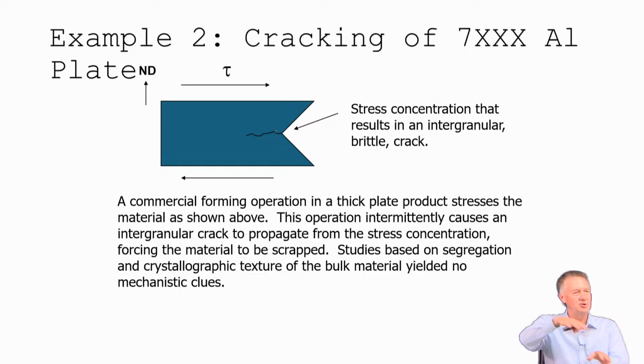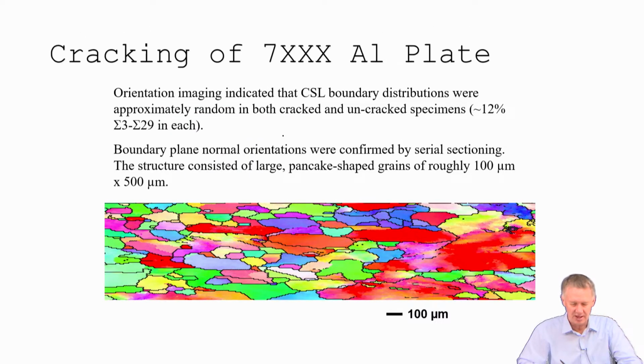They do the whole expansion procedure, and you get a crack, right, where you have an overlapping piece in your mandrel as you're expanding, so you have a little stress concentration. And if that happens to hit at a certain place that's susceptible to cracking, you get a crack through the plate. Sometimes you get a crack, sometimes you don't get a crack.